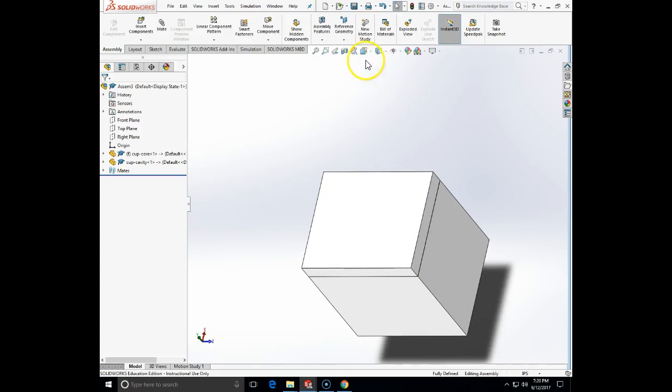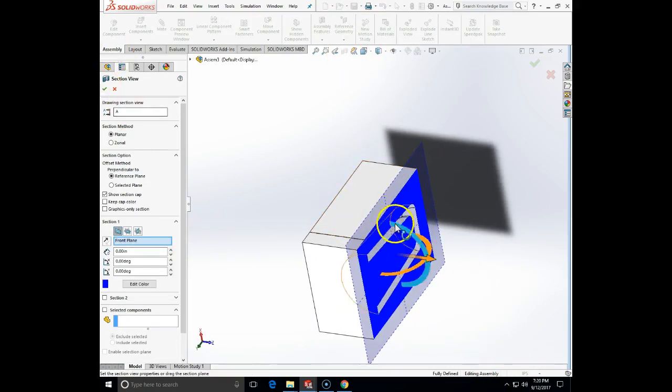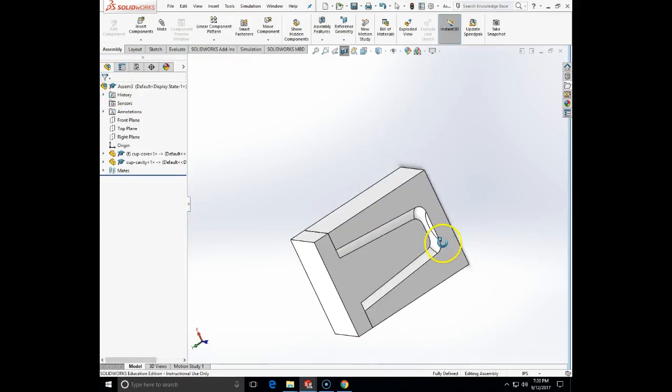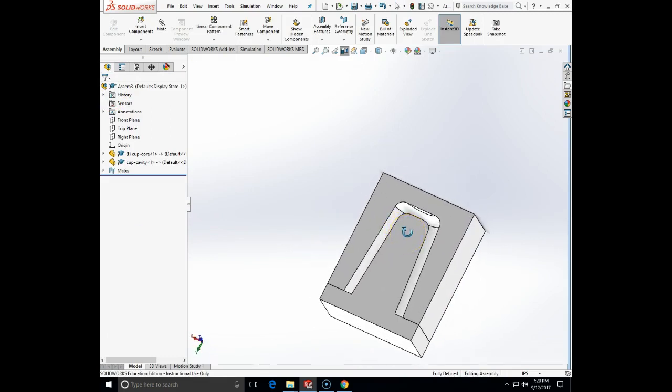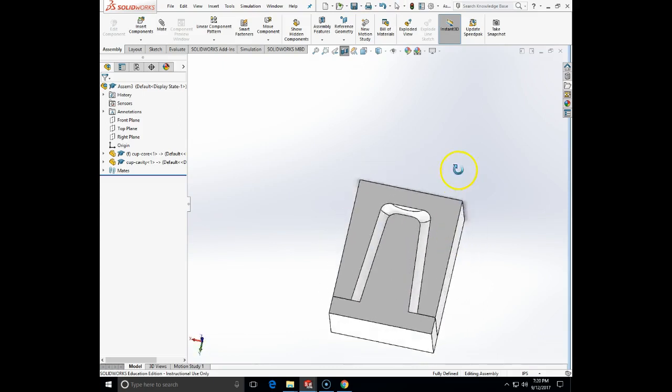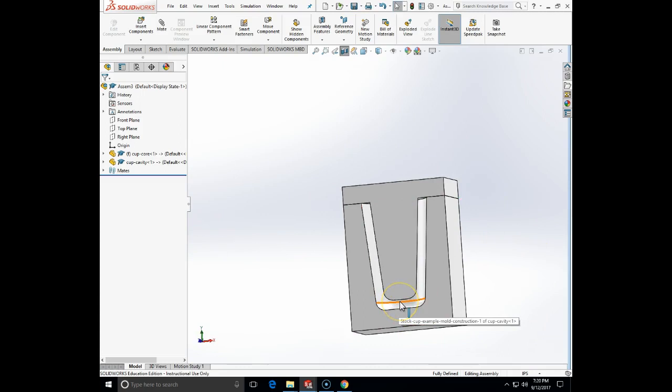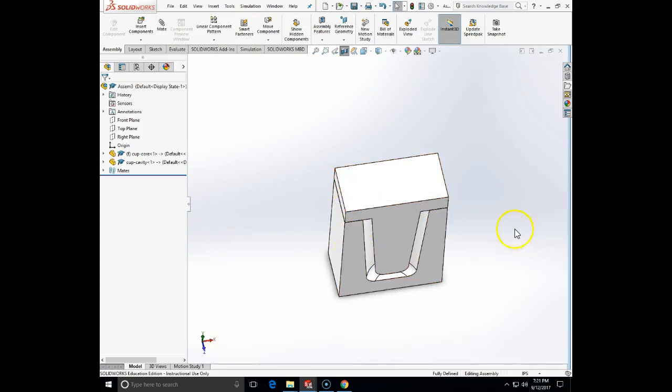Now, if I look into the cross section, look what I have inside those bricks. I actually have the air pocket, which is in the shape of my cup that I want to start casting. So what I need to create now is a way to bring the material in, and usually you want to bring the material in at the lowest point in the mold. Why? Because you want the air to be displaced from bottom to top. At the top, I'm going to make some vents which are going to let the air get out. And then I will need to make some, let's say, 3 or 4 holes, which I will use to align and also to hold this mold together.